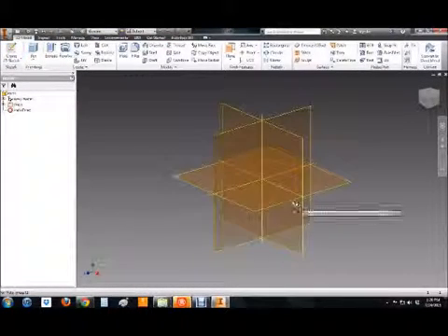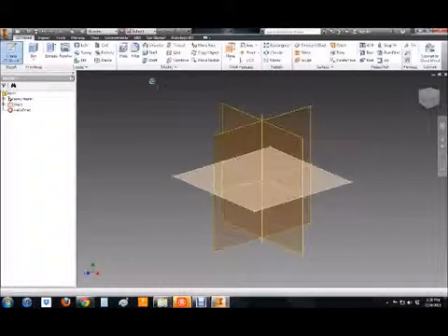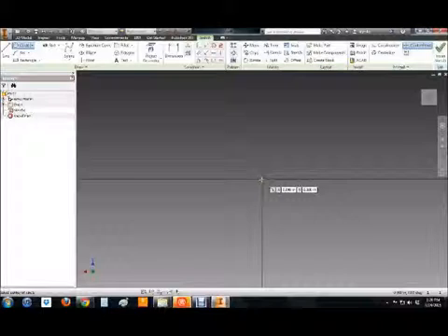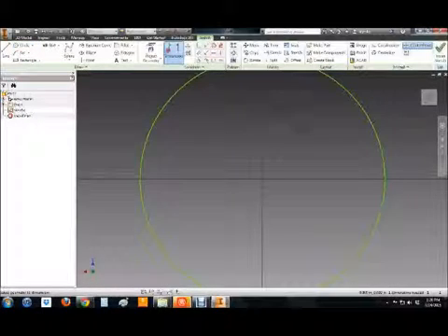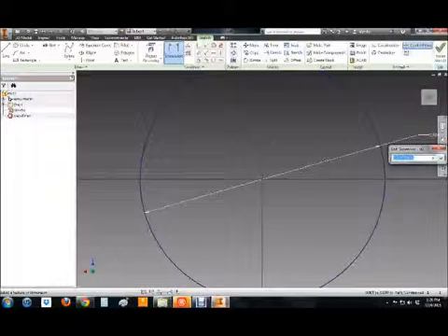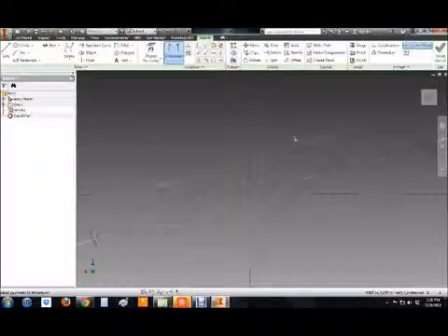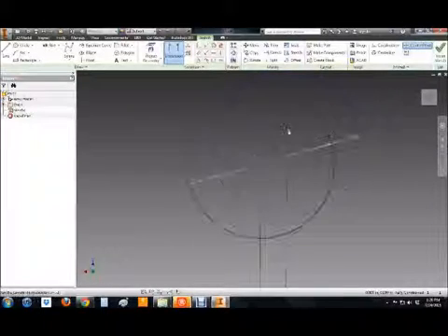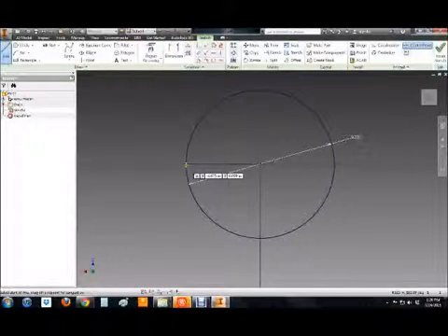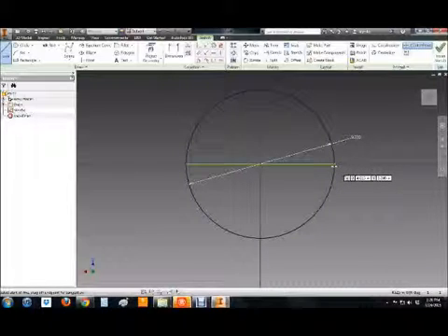Create 2D sketch. We're going to make a circle. Draw it, any dimension. Then we're going to dimension it, and we're going to make it a diameter of 9.23. Now, 9.23 is a good thing because that's the actual size. The problem is that when we bring one into the other, they're not going to talk, because we have a 9.23 diameter basketball and a body that's only 5 inches tall. So we've got to be able to scale that when we bring it in.